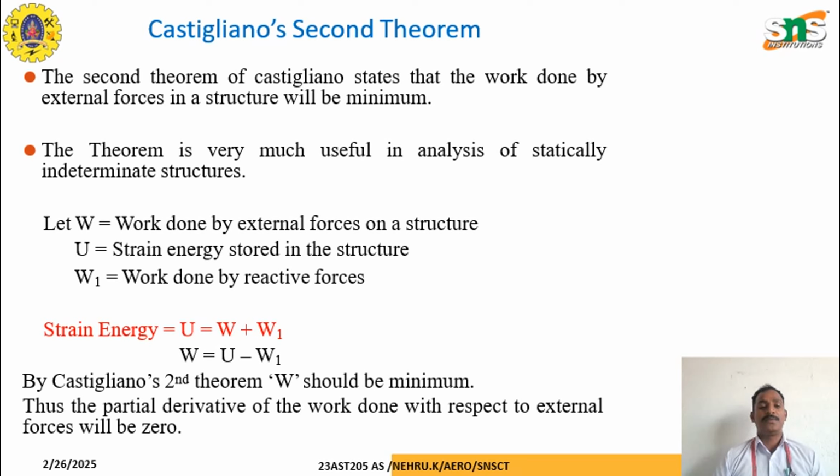The theorem is very useful in analyzing statically indeterminate structures. W2 is the work done by the external force on the structure. U is the strain energy stored in the structure. W1 is the work done by the reactive forces. Strain energy U is equal to W1 plus W2.